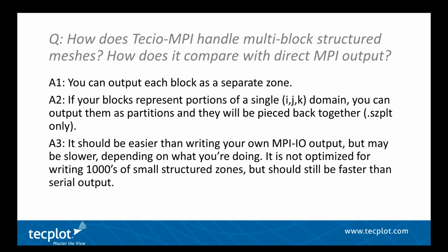So now we have had somebody tell us that they can optimize their Lustre file system, right? Or they can change parameters to improve speed? That's right. One of our customers achieved roughly an order of magnitude speed improvement by changing from the default striping to 64 stripes, which I think was the maximum for his particular file system. So I definitely recommend you check the documentation or check with the system administrator, if you're using a parallel file system, and increase the striping for your TecIO output.